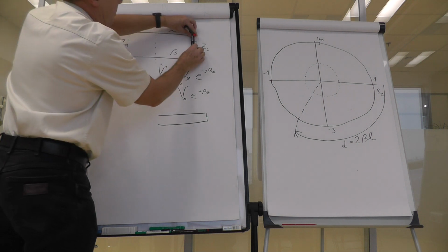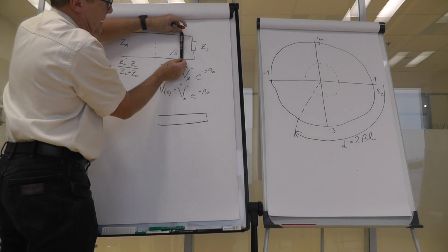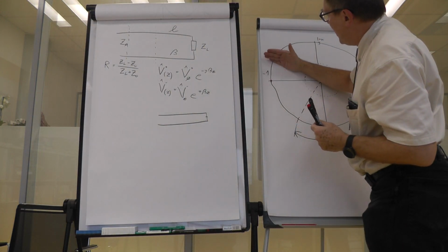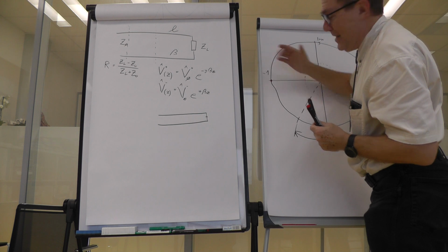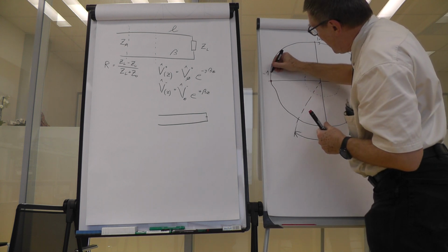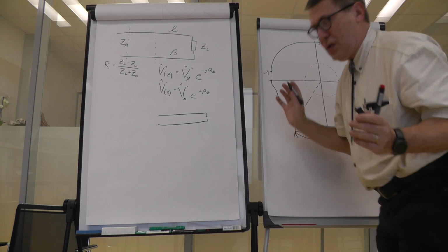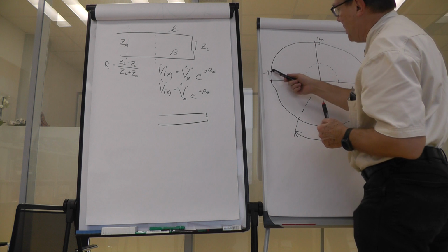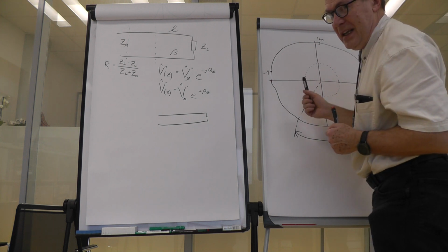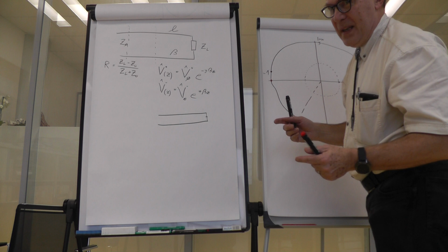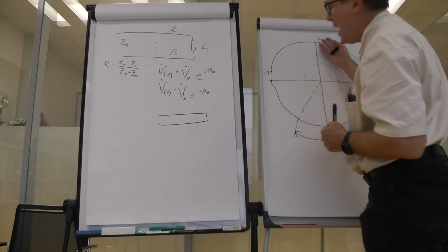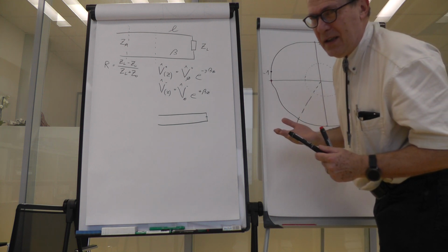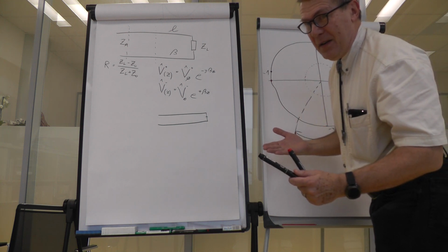What would happen if you have a perfect short here and you observe it from some distance? Well, okay, the perfect short would be a little bit rotated in this graph, so what you would see is not a perfect short, but this. It is close to a perfect short, but it's not a perfect short. Well, in fact, this impedance would be not 0, but would be imaginary. And what is the imaginary value significance?